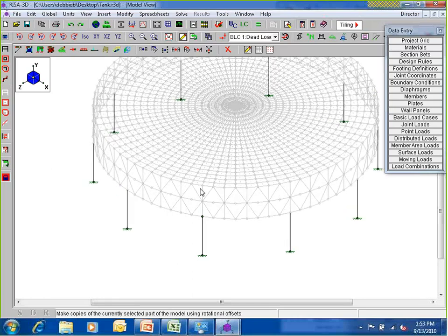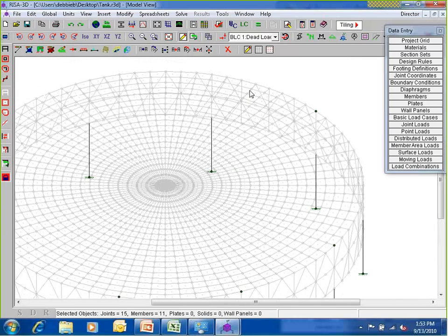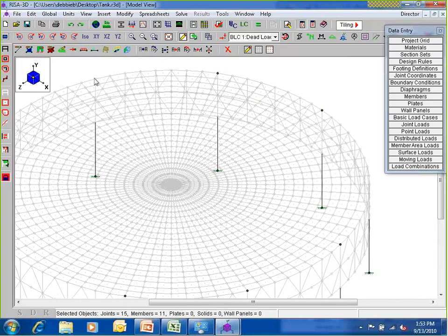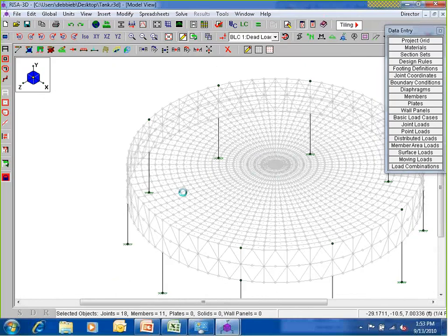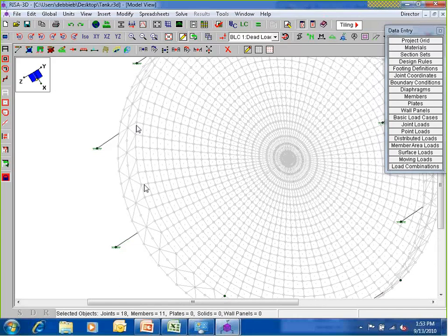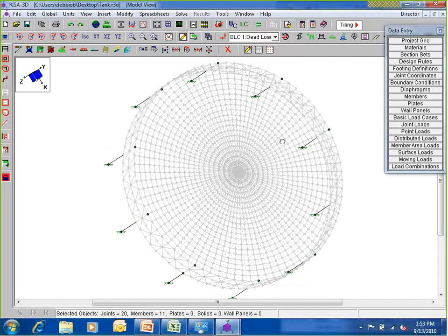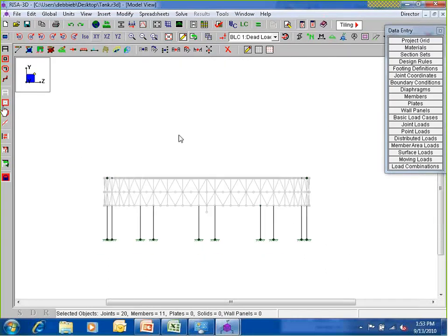One of the things I do need to do is draw in a little bit of support above the tank there, because we are seeing a very large tank. So I'm going to draw in some wide flanges above that. What I'm doing right now is selecting that node directly above the columns, so that I have a nice load path here. If I wanted to, I could maybe make these verticals a little stouter directly there, as they are going to be right in the midst of that load path. But we'll skip that right now.